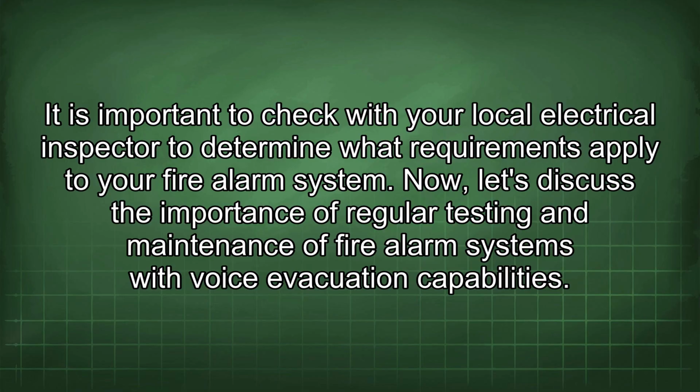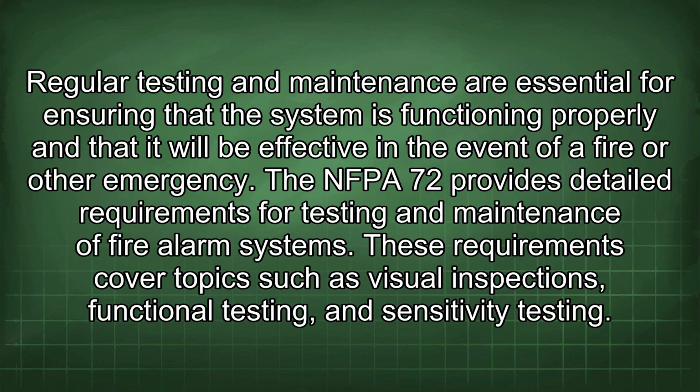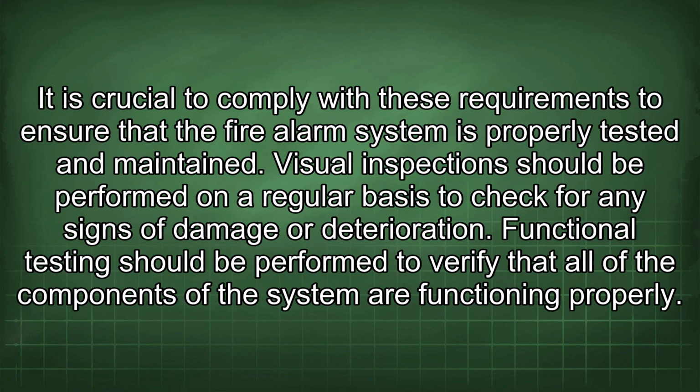Now, let's discuss the importance of regular testing and maintenance of fire alarm systems with voice evacuation capabilities. Regular testing and maintenance are essential for ensuring that the system is functioning properly and that it will be effective in the event of a fire or other emergency. The NFPA 72 provides detailed requirements for testing and maintenance of fire alarm systems. These requirements cover topics such as visual inspections, functional testing, and sensitivity testing. It is crucial to comply with these requirements to ensure that the fire alarm system is properly tested and maintained.